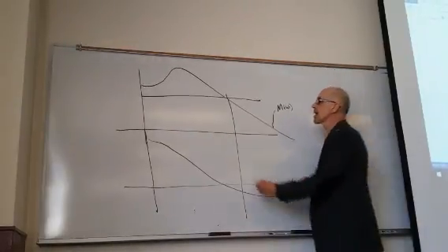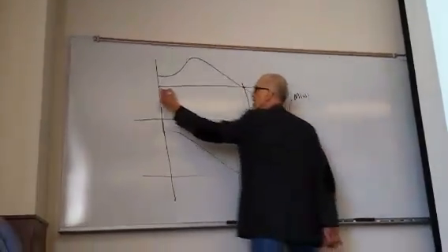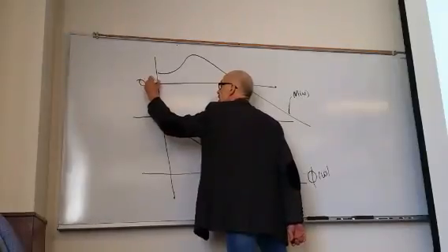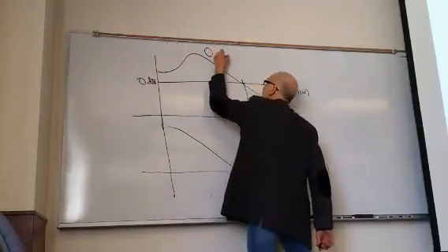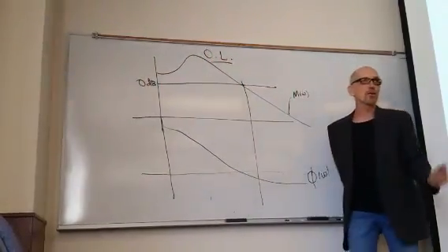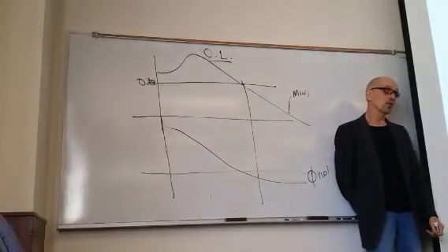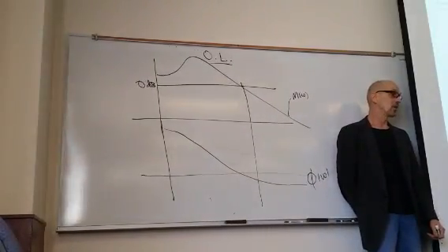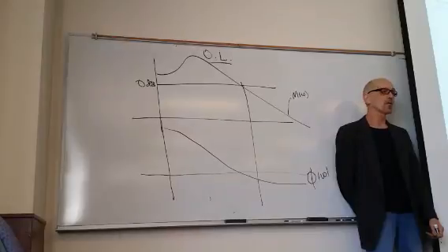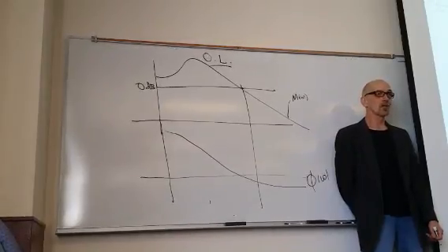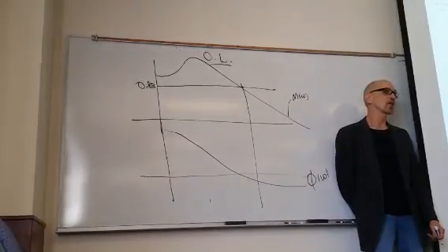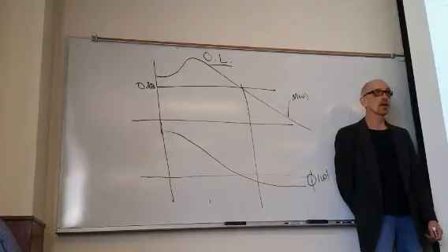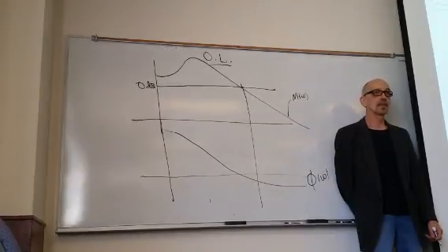So how do you do that? You go to the gain crossover frequency, which is 0 dB. This is open loop, by the way. Remember, we're getting closed loop information from the open loop. Don't forget that. That's huge. Simple concept, but boy, if you start using the closed loop system FRF to get the phase margin of the closed loop, the whole thing goes to Hades in a hell basket.